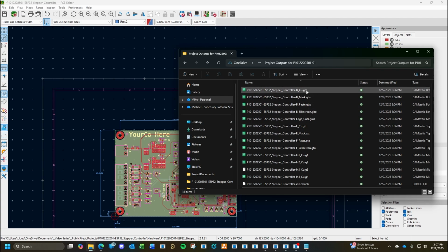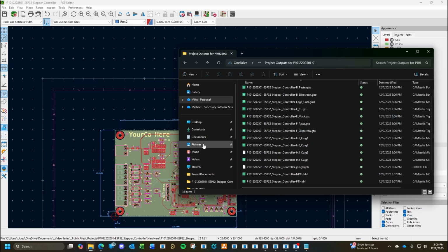So bottom layer, bottom solder mask, bottom paste mask, bottom overlay, GM1. That is basically general mechanical layer 1. Top layer, top solder, top paste, top overlay. These are internal plane layers, plane layer 1, 2, you know, not necessarily plane or signal, they're just internal layer 1, 2, 3, and 4. That's fine as long as everything's right.